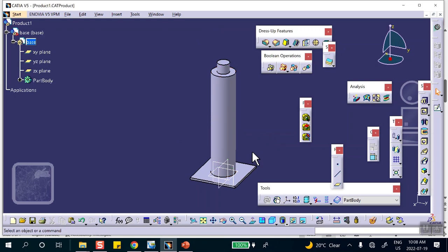Now, this guy doesn't go anywhere. That's the base of the structure, the base of the assembly. And that path, that seam that is going to be welded is not going to go anywhere either. So I can make that seam as a separate part, insert a new part and draw that, or make it part of this. So right now I'm going to do that. That path, I'm going to put it as belonging to the base, okay? Because they're both stationary, they don't go anywhere.